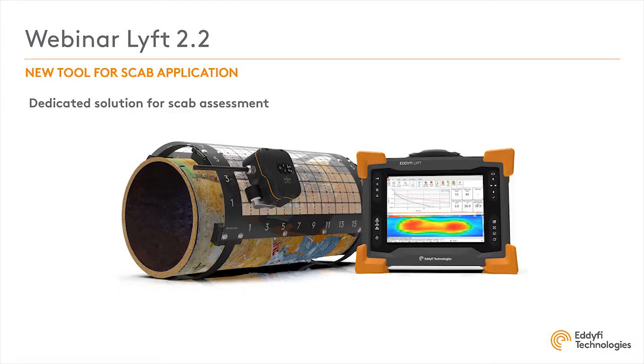This new probe is a dedicated solution for scab assessment. It gives the best estimation of the remaining ligament under scale corrosion. It's a safe assessment of the remaining wall thickness over scab while the asset is still in service. There is no need of surface preparation, you don't have to remove the scale, and there is no radiation associated with the use of that probe.